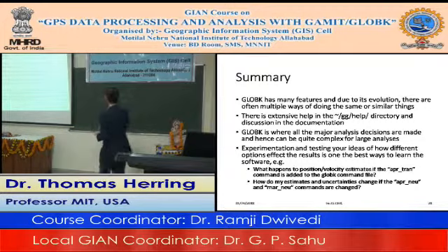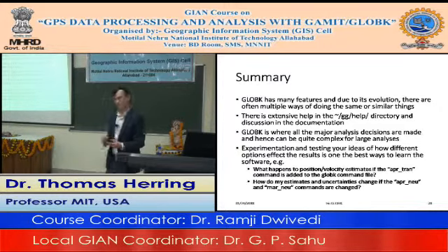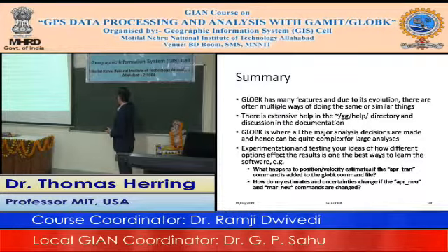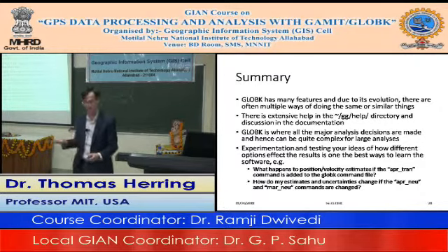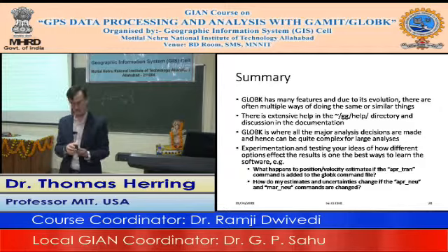Now, in general, when we do the overlap, we actually overlap a couple of stations for redundancy. And in theory, when we combine, we can break that overlap by renaming one of those overlap stations in one of the networks to a different name. And then it's like a different station. So you can play around with this if you want to. And again, that's the sort of thing we recommend that people do.